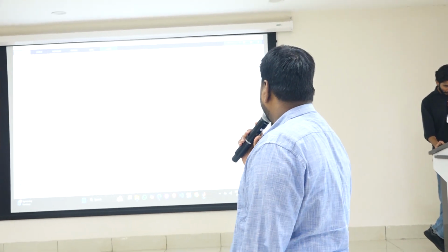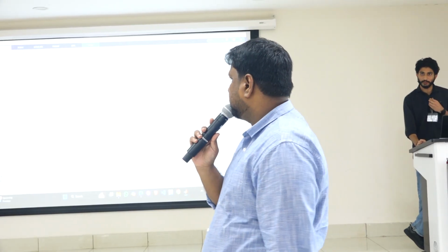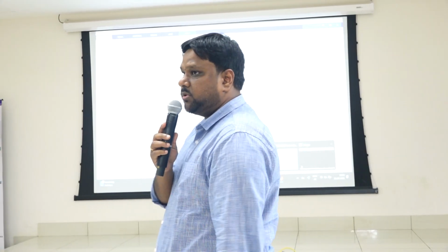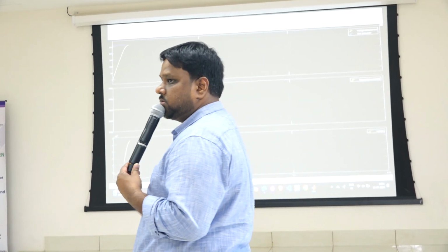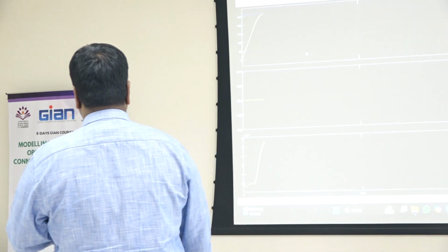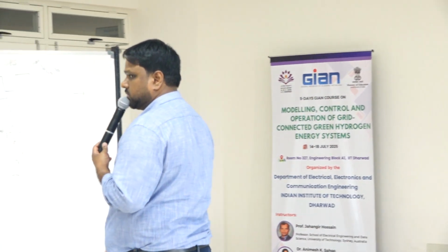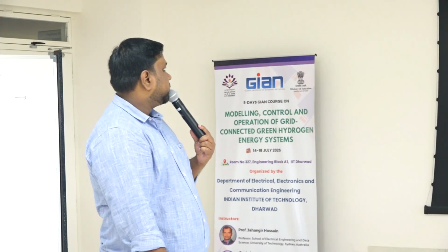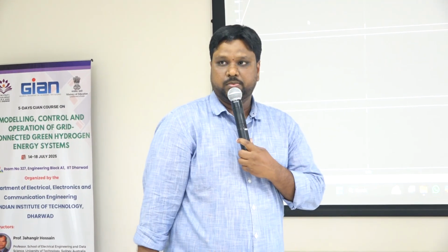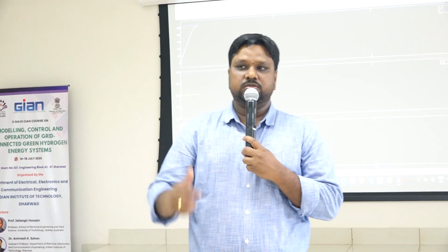You know the DAB converter power rating we put is 500 kilowatt, right? Power is 500 kilowatt, voltage is 262. Power is the multiplication of output voltage and load current. Power we calculate as output voltage into output current, load current, as DC power is V into I, right? Now you see the yellow is tracking the blue one. And at 0.05 we will have a jump, a step down in the reference voltage, and we will see what is happening to power and output voltage.